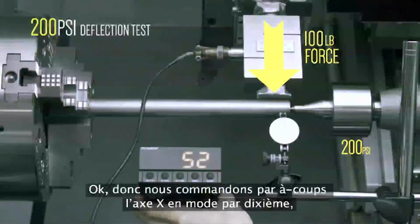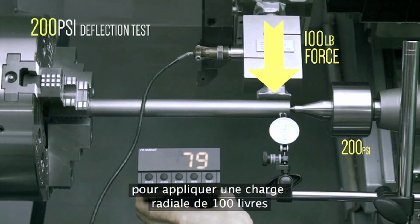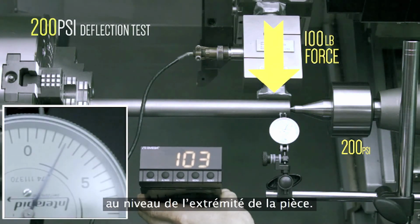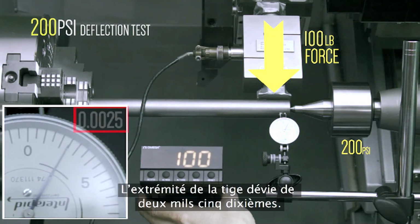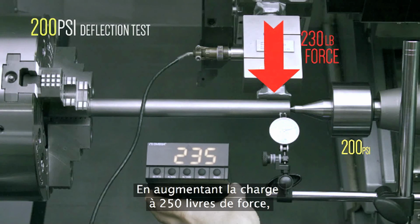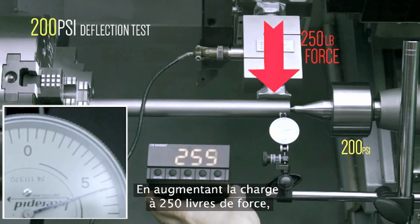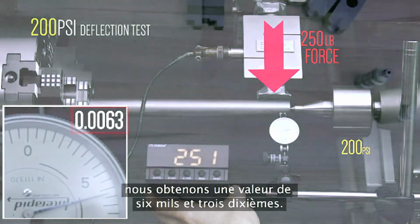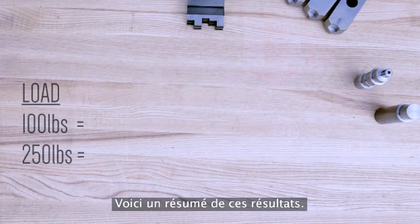Okay, so we're jogging x-axis in tenths mode to apply a radial load of 100 pounds at the end of the workpiece. The end of the shaft deflects 2 thou 5/10. Increasing the load to 250 pounds of force, we get a reading of 6 thou 3/10. Here is a summary of these results.